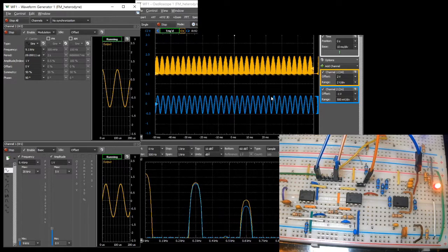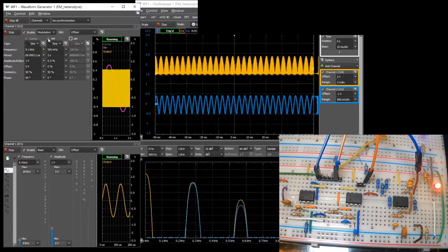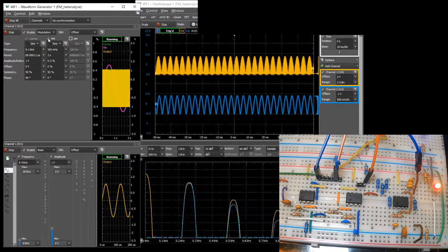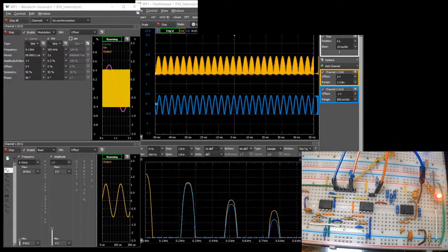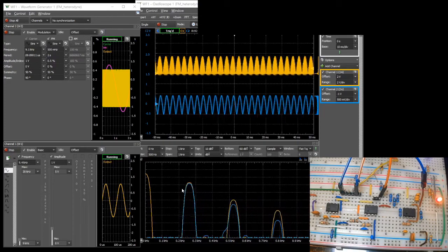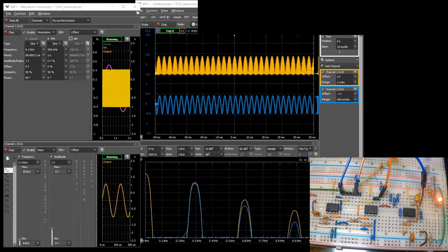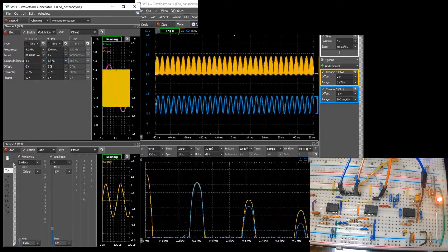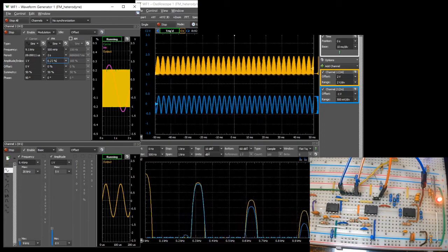The frequency modulation can now be turned on to simulate data, and the heterodyne signal carries the data signal. Demodulation can be performed as previously, but on a much lower frequency range. Since the heterodyne frequency is very low compared to that of the carrier, small relative FM amplitude on the carrier, for example, a few tenths of a percent, becomes large on the heterodyne signal, facilitating FM demodulation.